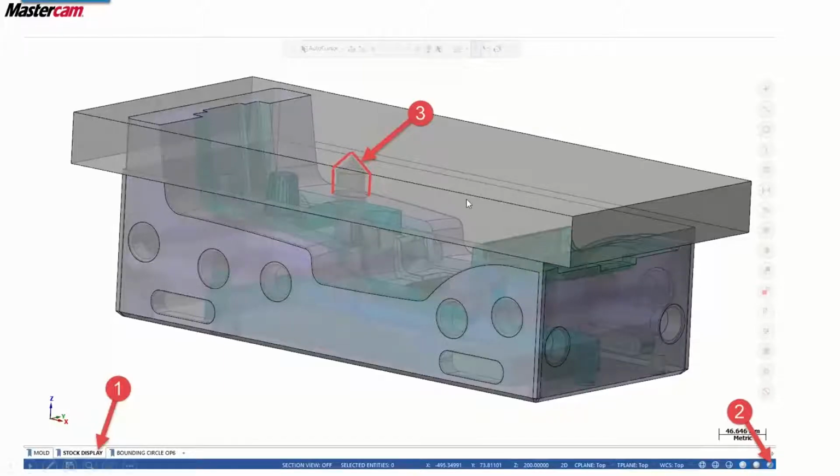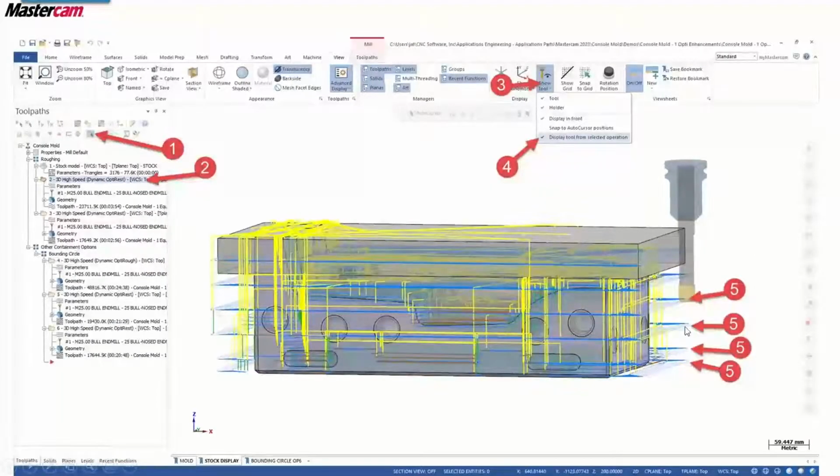And Mastercam now is going to be able to know that we have this undercut stock. Old school way of doing things, Mastercam didn't know. After it took off this material on top, look at all this air cutting going on down here. Mastercam was not intelligent enough to know that there was no material. It thinks that this box of material continues on all the way down to the bottom. Not so. We went in, we've made a stock model, and we're going to use undercut stock.